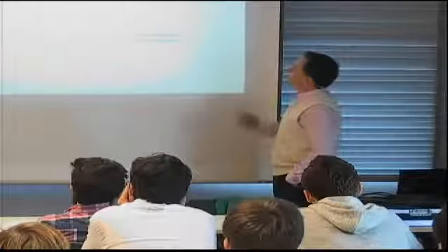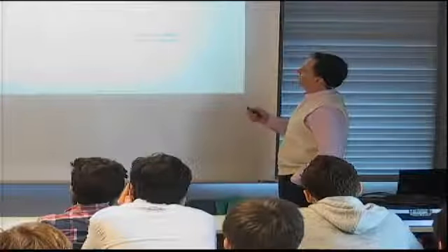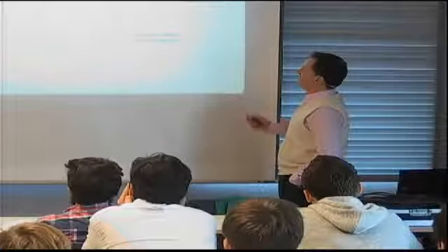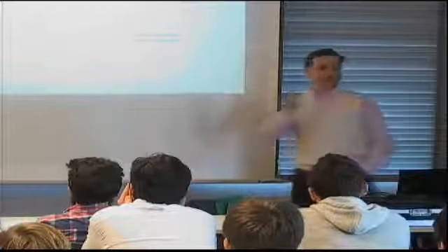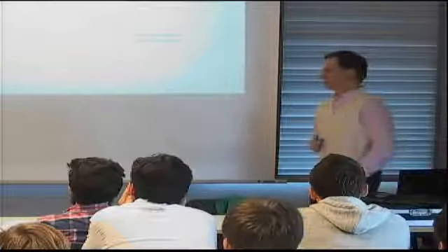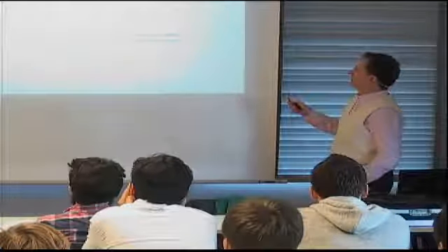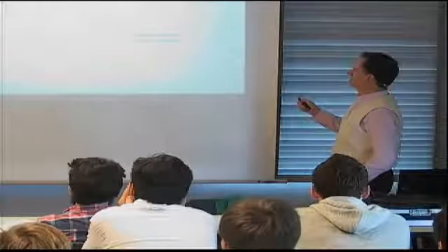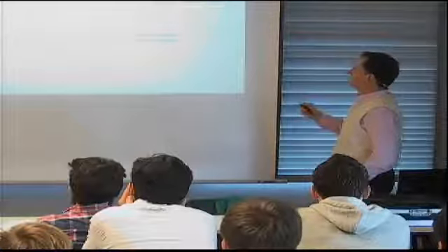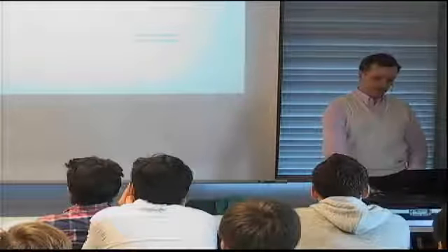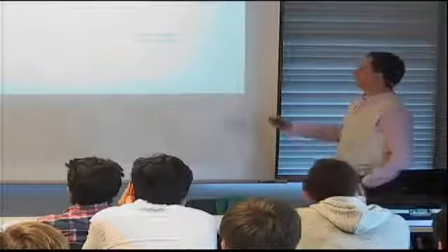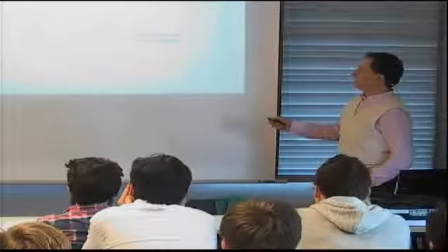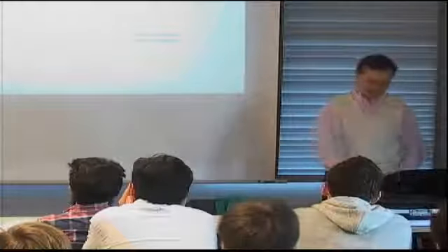So the A matrix and D matrix are given here. Notice web and stiffener have the same stacking sequence. This is not the most efficient, but just for the purposes of the example. And the corresponding membrane Young's modulus and bending Young's modulus are shown here. Thickness 1.37 millimeters, and my zero fibers are aligned with this direction 1 here.